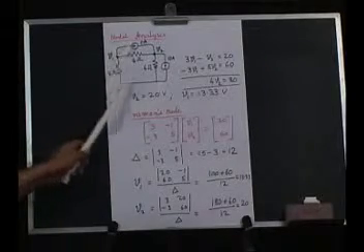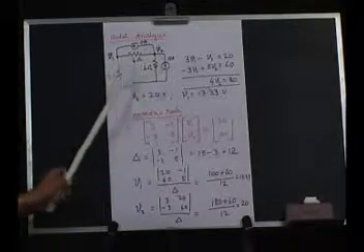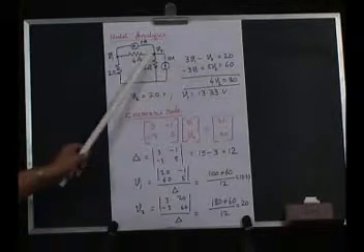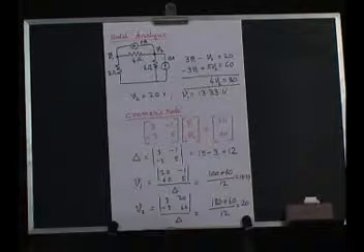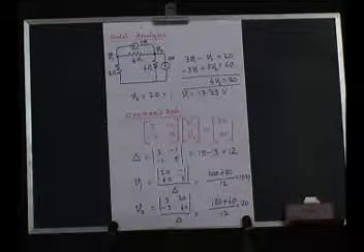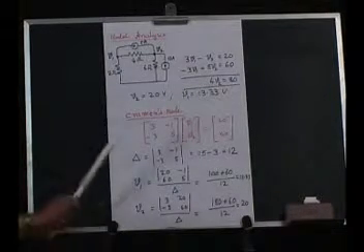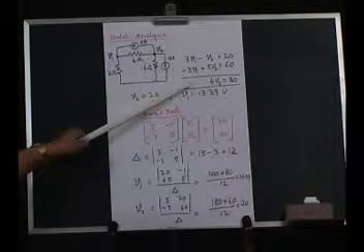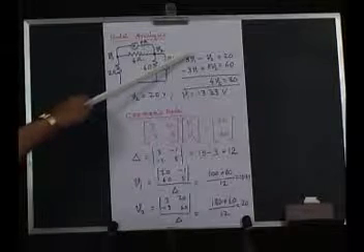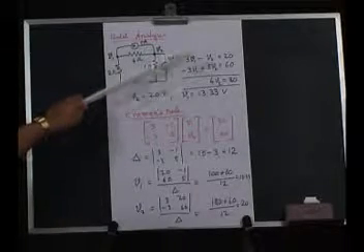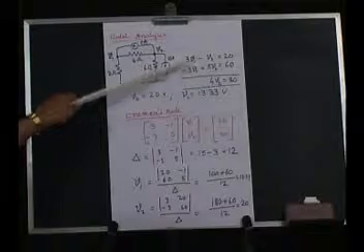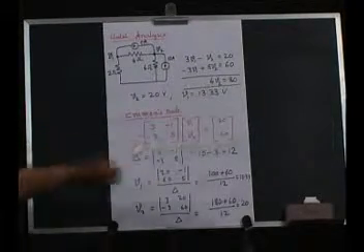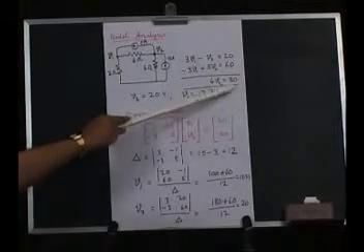The same circuit I have drawn here, the previous circuit, and the two equations we got from the previous discussion, I have written here separately. Then we can find the values of V1 and V2 by the elimination process. Let us say we can eliminate V1 because there is a positive 3V1 here and a negative 3V1 here. Suppose we add these two equations, this will get cancelled and we get 4V2, which is equal to 80.